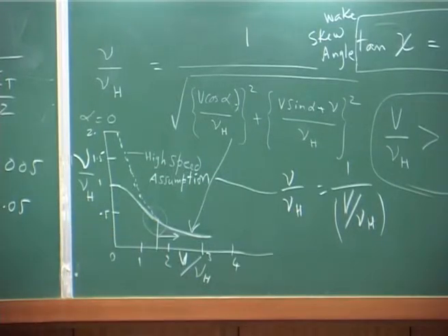If you take lambda h as root of Ct by 2, you get this. So V over nu h you can non-dimensionalize as mu over lambda h. It is greater than 0.075 precisely, but you normally take greater than 0.1, okay.